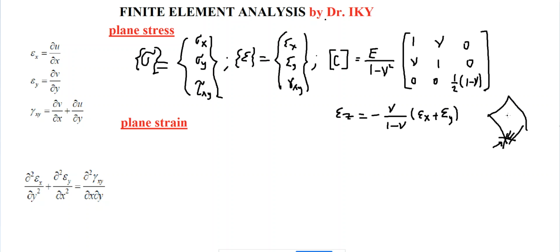It's like a shell, and because of that, we have, in plane surface, it means 1 or 2, or x or y stresses, which are sigma x and sigma y, and you have a shear tau 12 or tau xy, but we have no normal stress on 3 or z. It is the plane stress model.